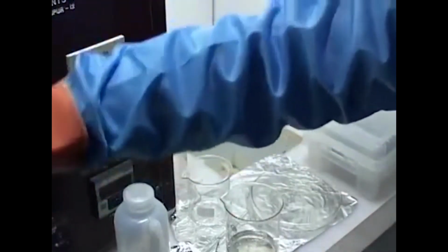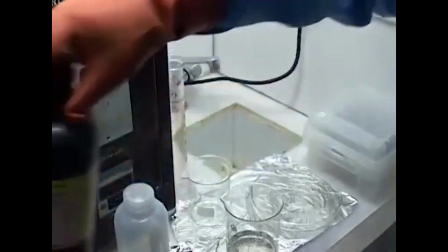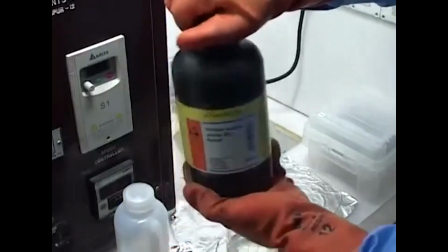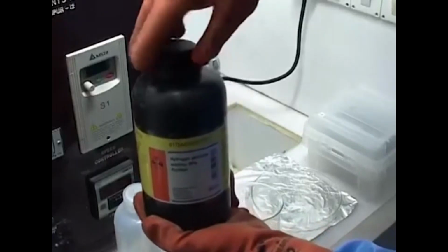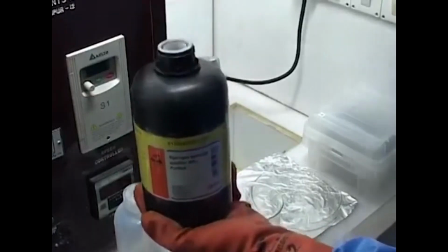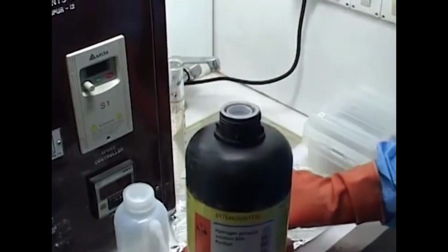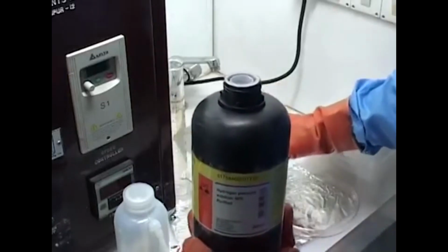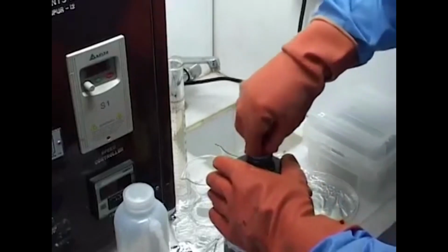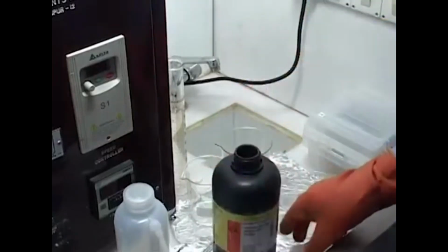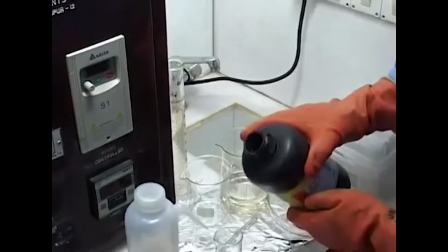So this right here is the container for H2O2, and the reaction is essentially an equilibrium reaction where a lot of hydrogen ions and hydroxides are generated, and essentially it's an equilibrium process which coats a layer of hydroxide onto the silicon dioxide, the nascent oxide surface, and also creates a lot of heat. Okay, so basically we need 30 ml of hydrogen peroxide. So we open this and pour exactly 30 ml of hydrogen peroxide into the secondary container here.